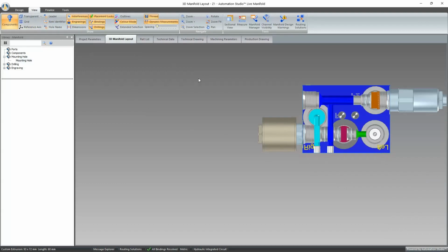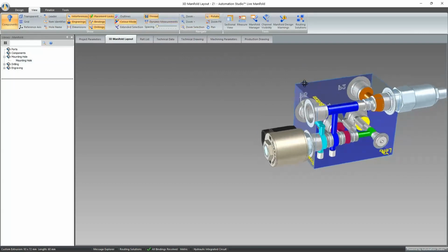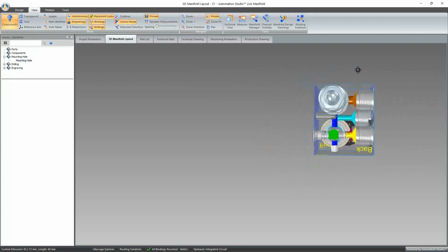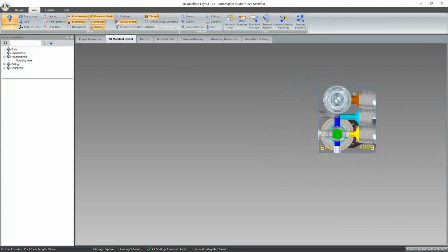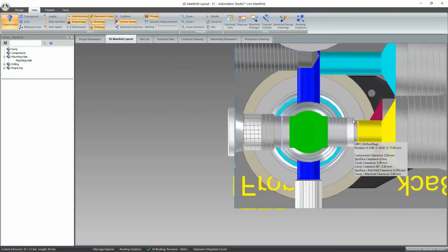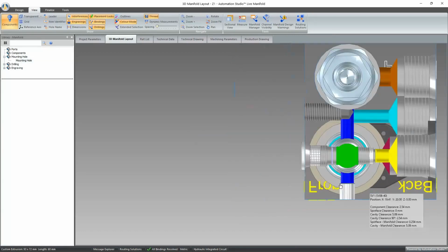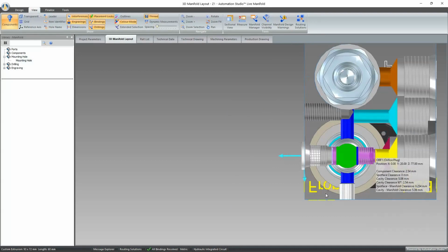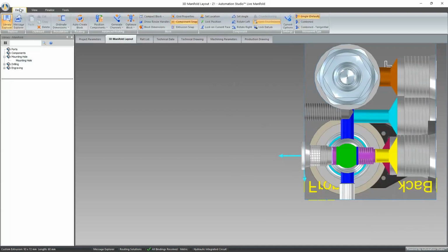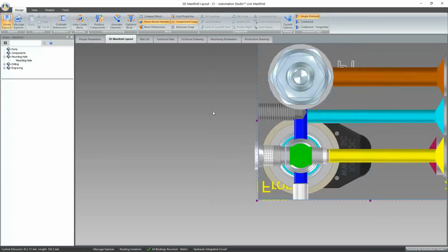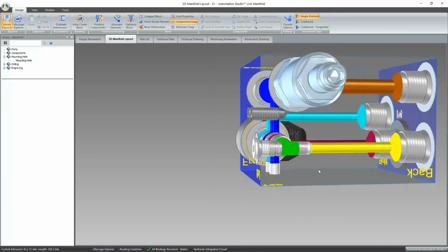The next thing that we can take a look at is the depth of a buried component, and how we can change that. We saw when I created my block, I added this orifice plug, an NPT orifice plug, so you can see there's a taper to it. I can modify its depth. First, I'll show my resize handles, just to increase the spacing of my block here.